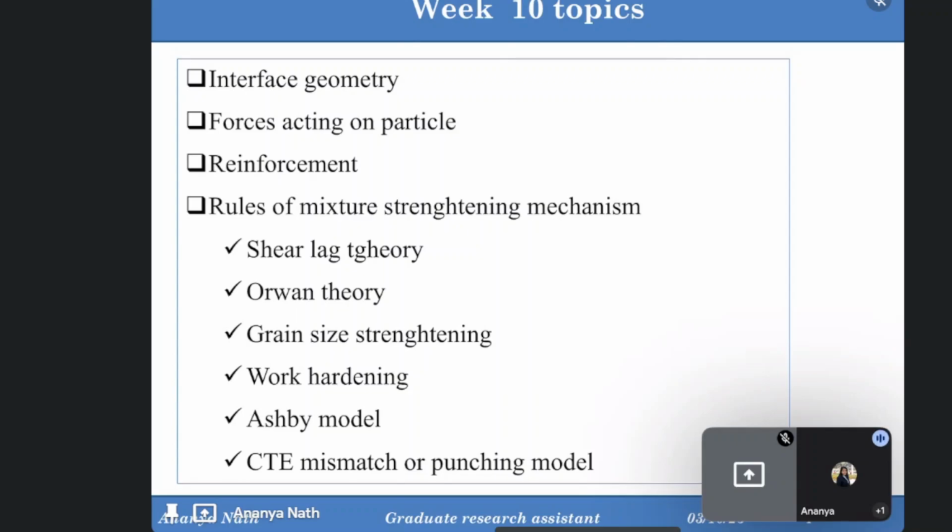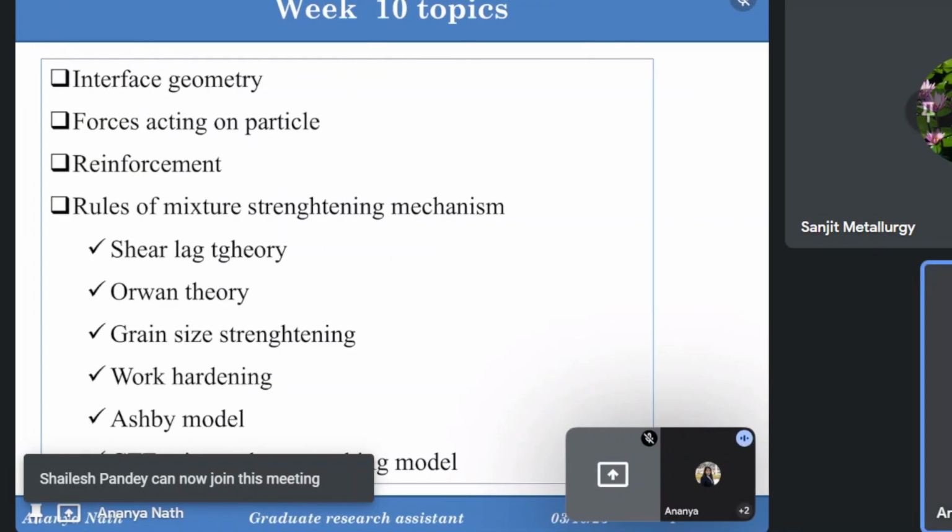There will be some bond in the interfaces, but it will not be like the reinforcement particle atoms will sit in the lattice. No, this is the case for alloying. In case of metal matrix composites, the reinforcement will have a lattice, and the matrix will have a lattice. Both lattices can be different or similar type, low mismatch or high mismatch or whatever.